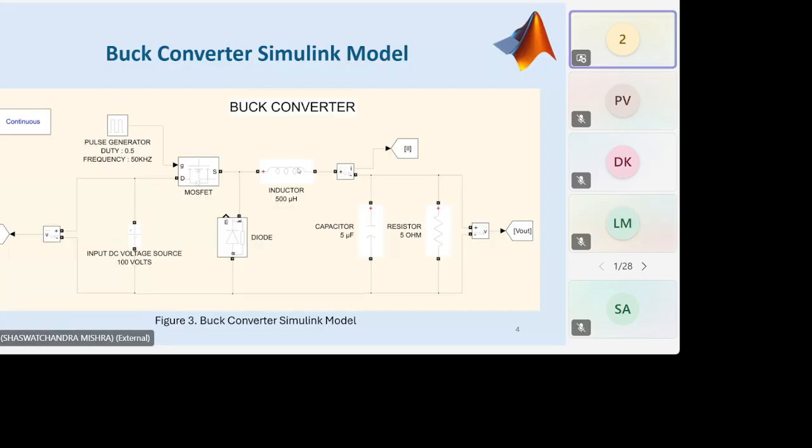Okay. So here we conclude our buck converter journey. Now we will move on to the design of its gate driver, right? So why do we need a gate driver actually? We want to give the MOSFET some duty ratio, right? Some pulses. It will be turned on and turned off for certain times. So in order to do that, we will be using a microcontroller. We will be programming a microcontroller such that it will provide a high pulse for some time, and then it will provide an off pulse for some time.